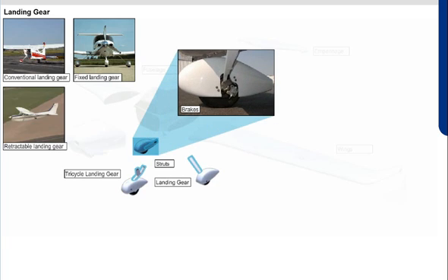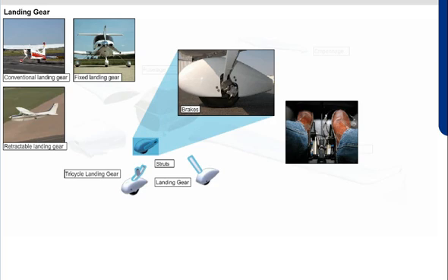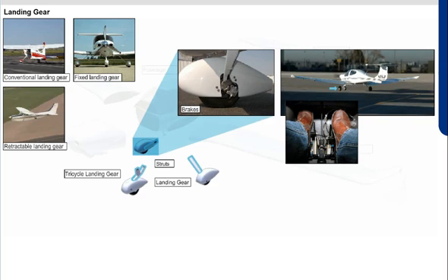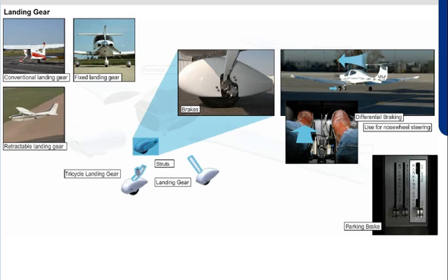Airplane brakes are located on the main wheels and are applied by using foot pedals in the cockpit. Foot pedals operate independently and allow differential braking, so you can apply varying degrees of braking to each wheel. During ground operations, depending on the type of airplane, you use either nose wheel or differential braking or both to steer the airplane. Most airplanes also have a hand-operated parking brake that holds pressure on both brakes to keep the airplane from rolling when your feet are off the pedals.